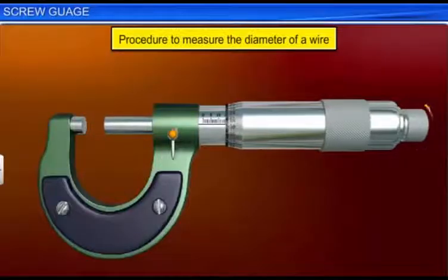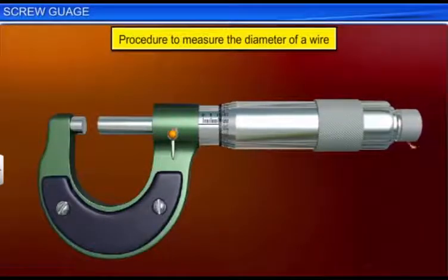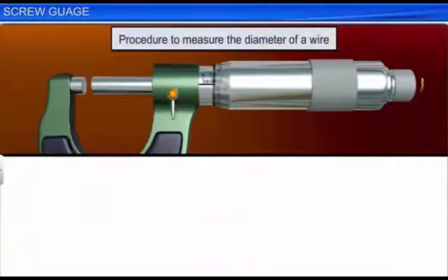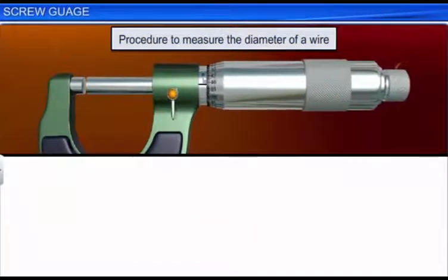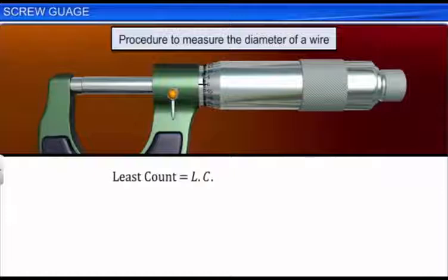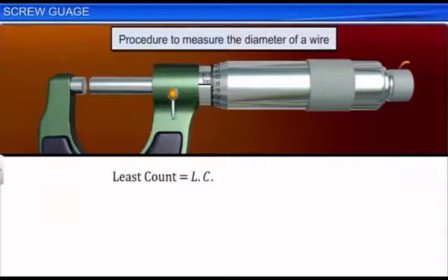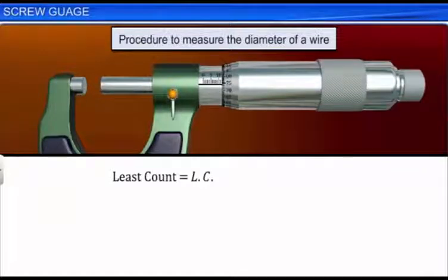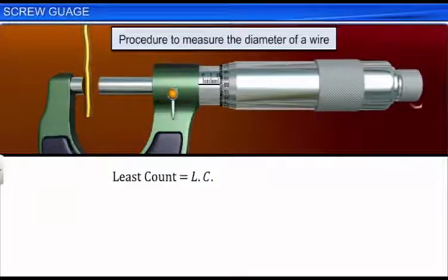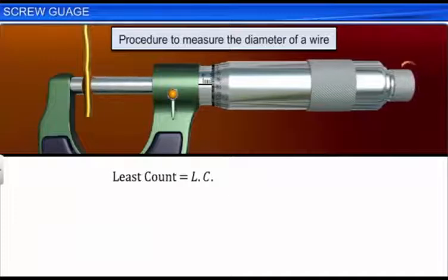Now let us measure the diameter of a wire with a screw gauge. After calculating the pitch of the screw, least count and zero error, if any, rotate the head scale anti-clockwise so that the shafts open. Place the wire between the stud and the tip of the screw. Rotate the ratchet clockwise so as to hold the wire tightly between the stud and the tip of the screw.